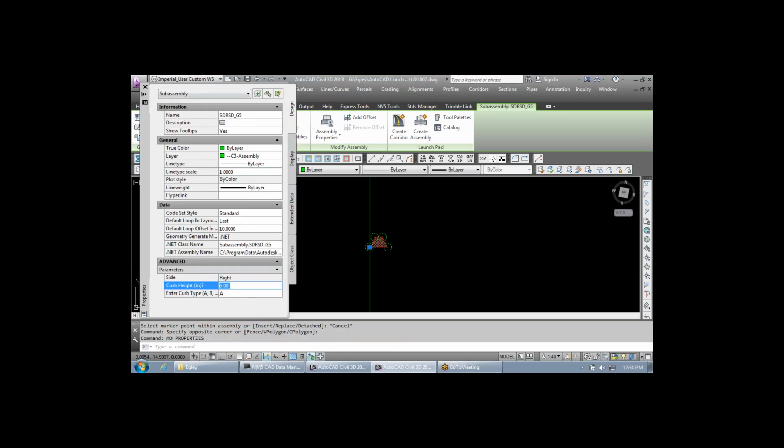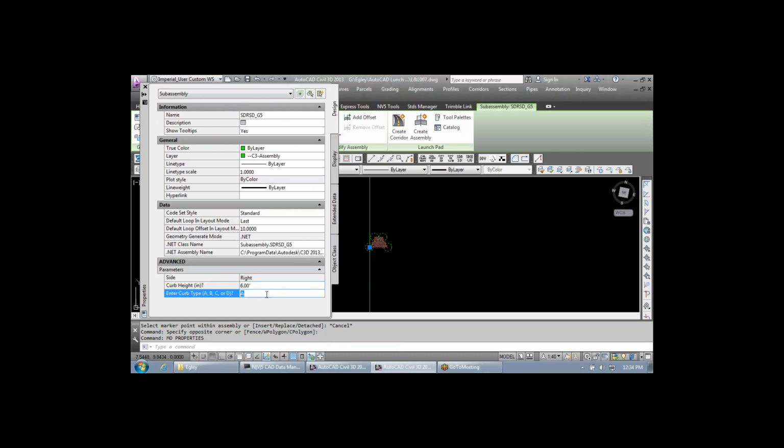Here you have your curb height that you specify. Let's say it was a 6-inch type B curb. Oh, that looks a little funny, right? Well, the reason for that is because there is no 6-inch type B curb. So you'll notice some visual display issues with that. But there is a 6-inch type C. There's not a 6-inch type D. So you do kind of need to know the standards a little bit. There is an 8-inch type B, and then everything adjusts and displays correctly.